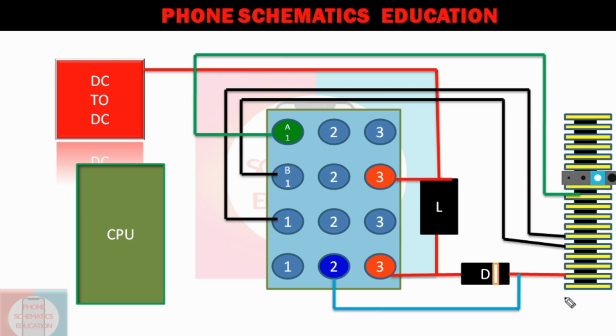First, multimeter on diode mode on a reverse bias, you did not get a value here, suppose OL. Now you will see in the schematic there is a 0 ohm resistance. Now check the other side of the resistance on diode mode. If you get a value, suppose 600, that means this resistance is open.